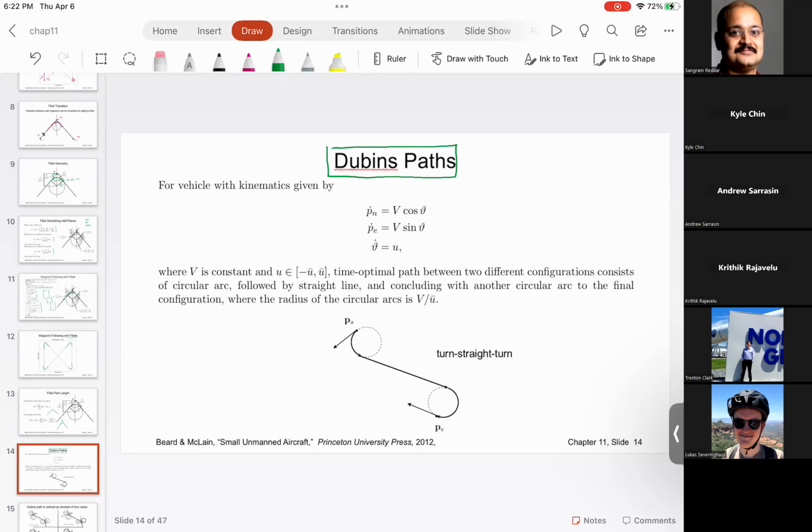So the idea is, instead of defining the path as we defined earlier, we define the path as the transitions of the states. In other words, we are going to come up with different configurations, and we'll try to find the most optimal configuration that is possible. A simple example: imagine this is the path. Here we have a left-hand turn, a straight line, and then a right-hand turn. This transition is given as LSR.